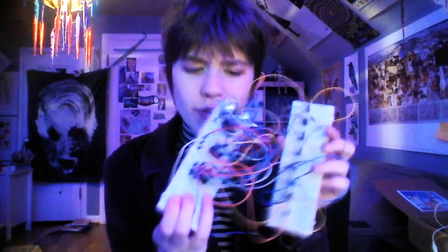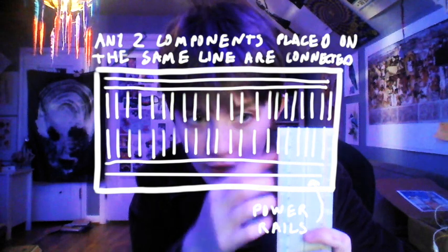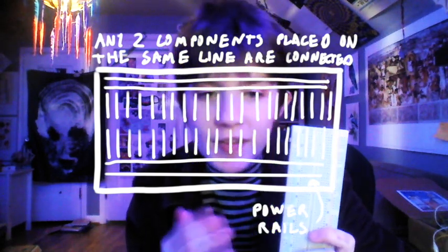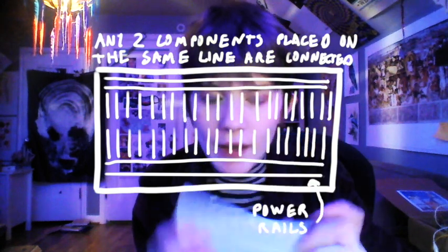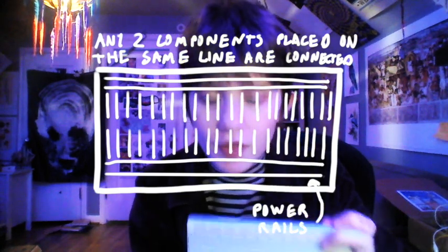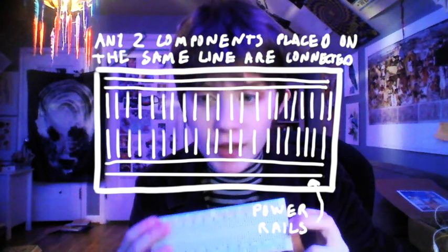These are breadboards. It's pretty much what you use instead of a ton of wires. This is what it looks like inside. Any component placed on one of the long gray metal rails will be connected to another component on the same rail. We can see that the rails on the inside are vertical, while the longer outside rails are horizontal. The horizontal ones are called power rails and are used to power the circuit through a battery connection.